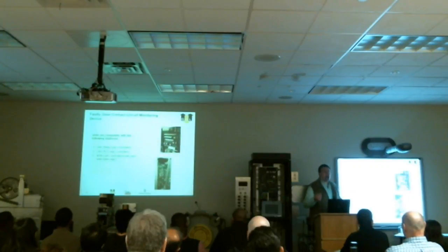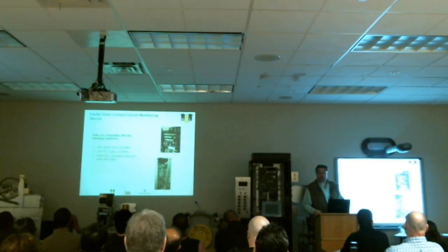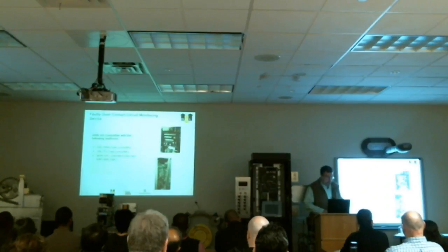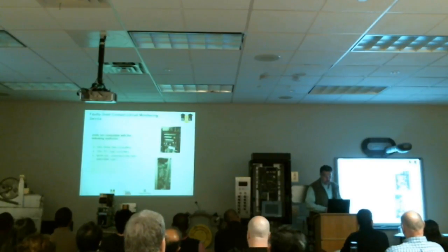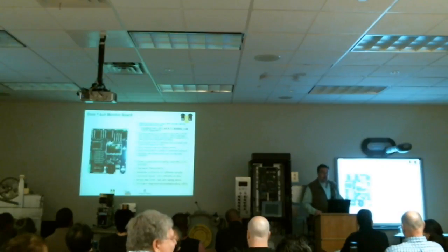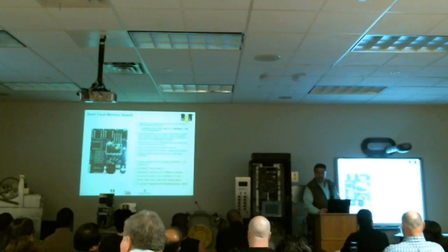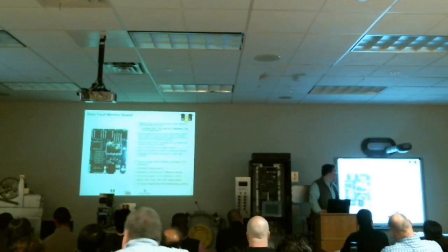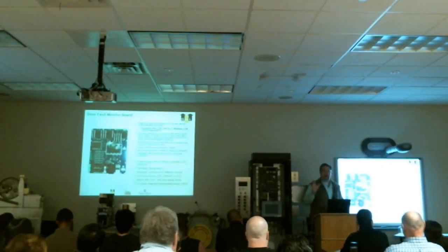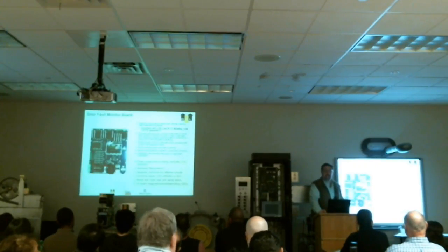Now, what about all other controls that are non-Galaxy related, such as GL relay logic controllers, PLC controllers, and non-GL controllers? What do we do to comply with door lock monitoring for those kinds of control systems? Put in a G4 if you can do it in the next 18 months, 40,000 elevators, yes. But if you can't, obviously, then you have another solution. And the solution is we developed our own door fault monitoring interface panel. Okay, that will interface and retrofit to any foreign equipment.